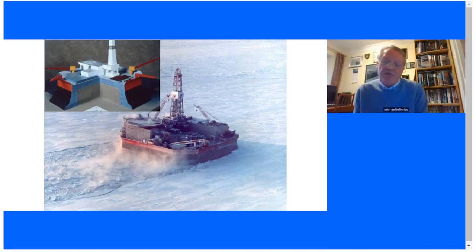Even though that structure looks impressive, and I should mention here that she's about 100 meters across on the waterline, it's actually just a giant box. Technically, it's a caisson, and we fill the center of the platform with sand. And it is essentially a giant shear box. And that is how come a geotechnical engineer like me came to be engineer of record for deploying this platform, because even though the steel looks impressive, the steel is just along for the ride.